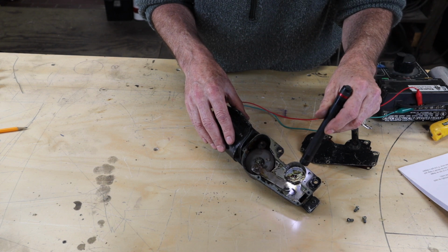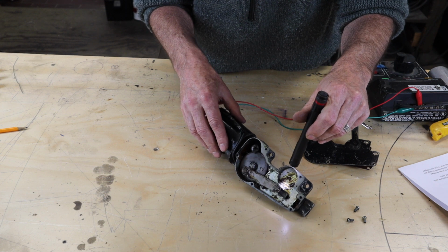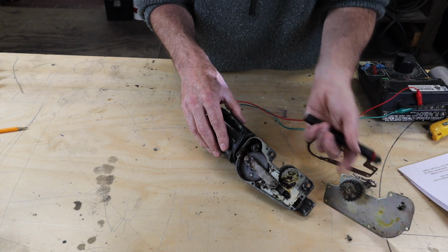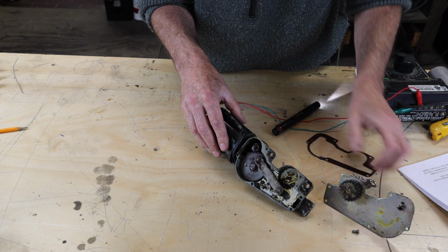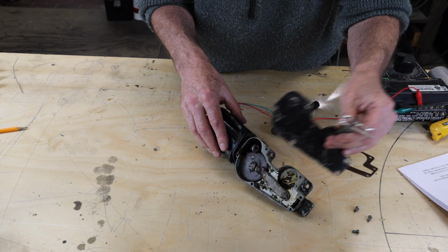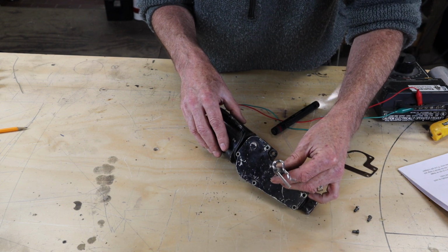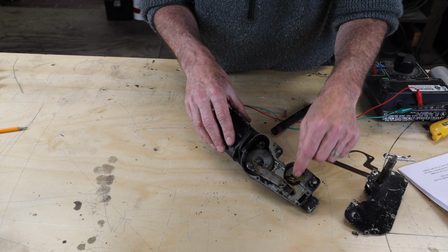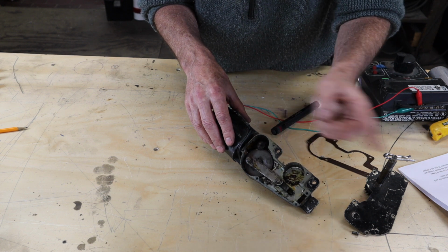And that gives us here, you can just about see that. You can see there's a rack and pinion because on the back of here is the pinion. So this in here is the rack. This is the pinion. So when we put them all together, we get the right speed at the right motion going the right way. And again, that's a worm drive to a spur gear reduction to a crank slider to a rack and pinion. And then to an armature on the end, which is the windscreen wiper arm itself.